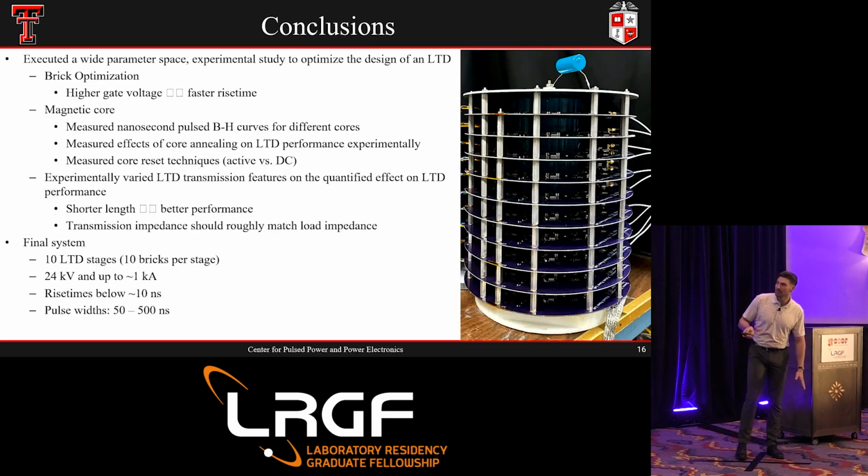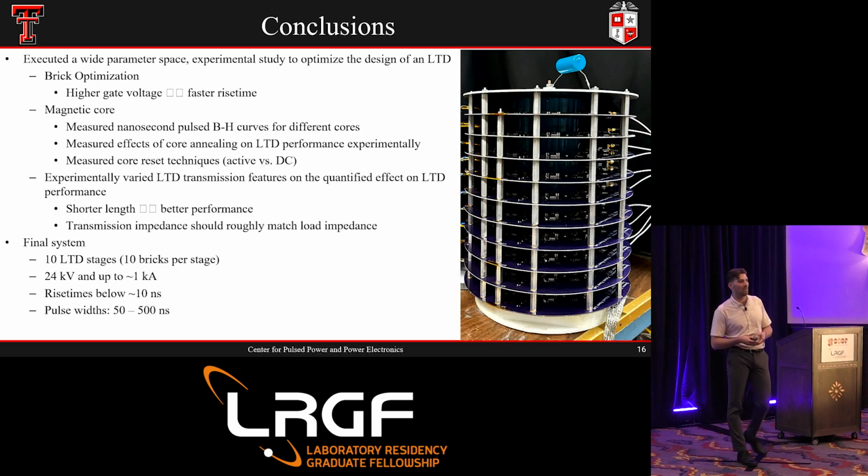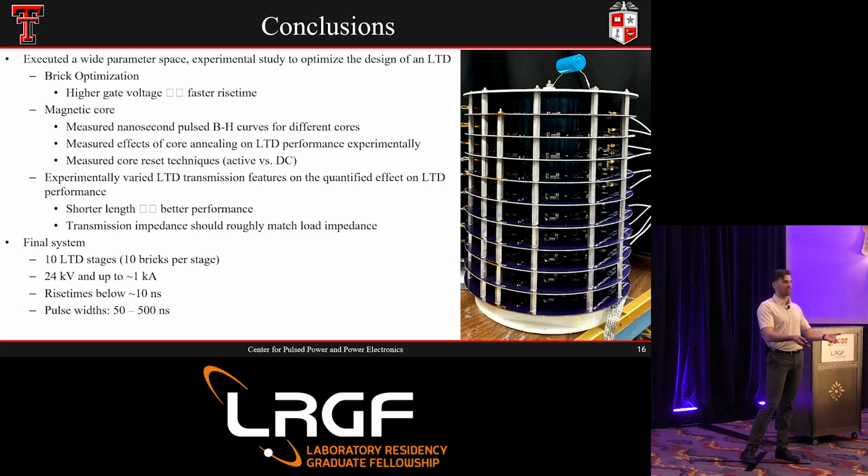With that, we looked at a wide parameter space, and we really were just trying to see what knobs we can turn on this general pulse power device to optimize it, as well as provide it. This was actually delivered to Nevada National Security Site for them to test with, so that was pretty cool. The final system was 10 stages, 24 kV, a kiloamp, and all the rise times were about 10 nanoseconds. And with that, I'm done.